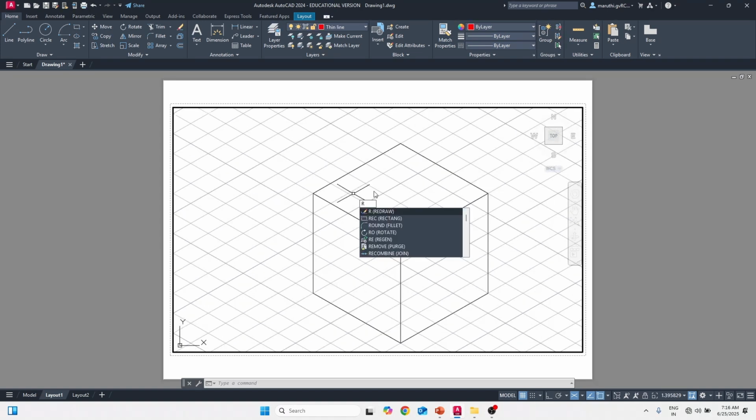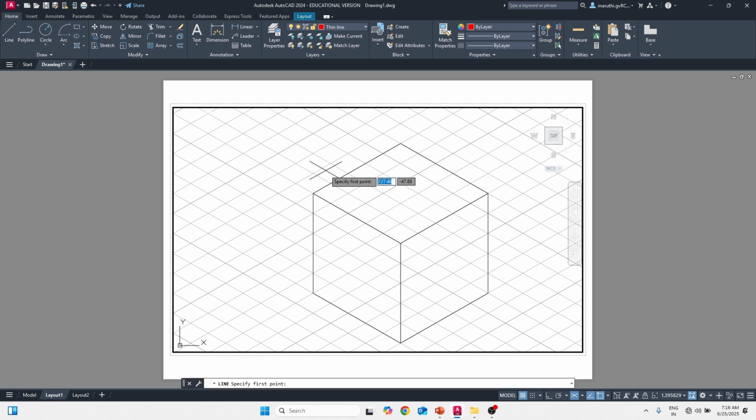Now this is the cube. Now over this cube only we are going to place the cone. Okay, and they have given the cone base as having a dimension of 30 mm. So I will go for the line command again. Now I need to find out the center. Okay, here I will go for the midpoint. So total is 50, right? Then the midpoint will be 25, right? Then again this is your midpoint, that is 2.5 boxes. Then again here. Now you got the center point.